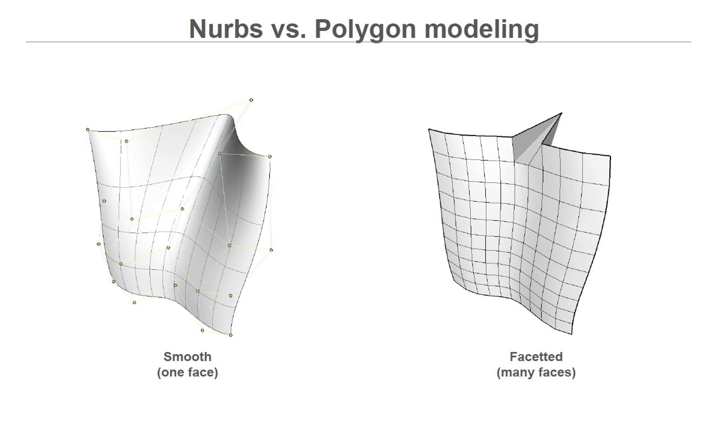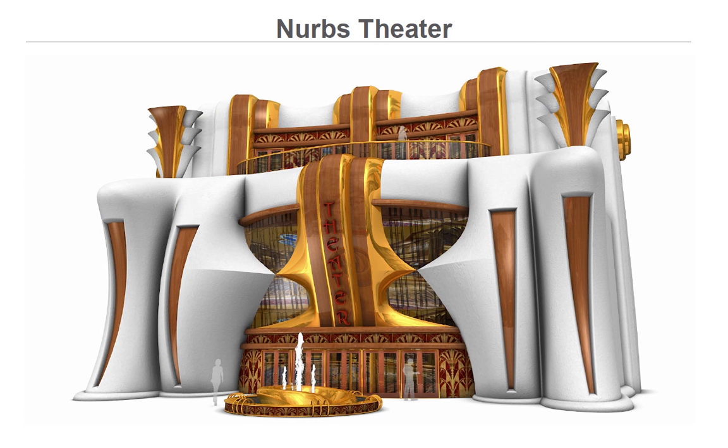Basically, a Nurbs object consists of a mathematically smooth surface that can be manipulated with a series of control handles and will always render infinitely smooth. A polygon object consists of many polygons, also known as facets, that define the overall shape. And the number of facets will influence how smooth the surface appears when rendered. There's advantages to both types of geometry, and that's why formZ 3D and formZ let you work with both. And it should be mentioned that any smooth Nurbs object can be converted into a faceted object using the Convert tool.